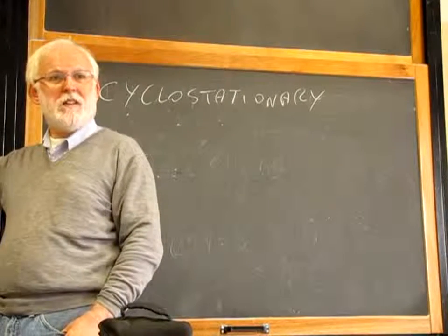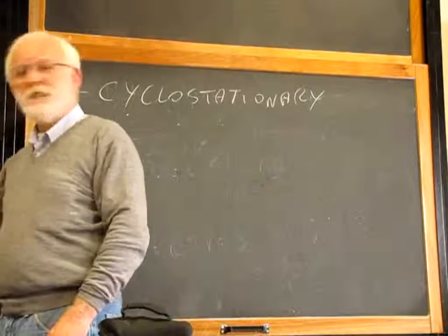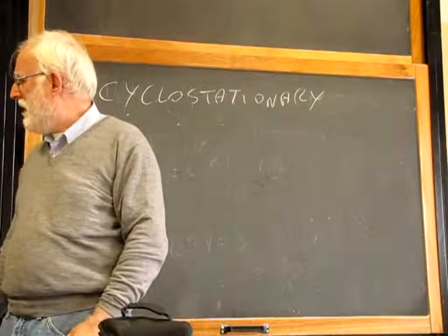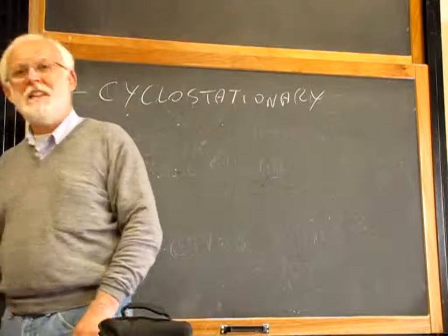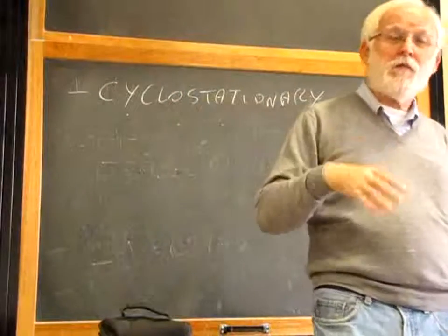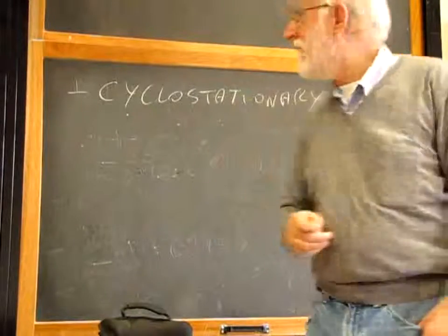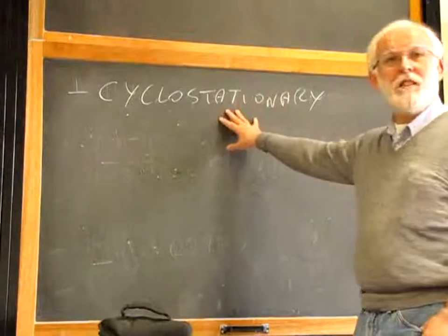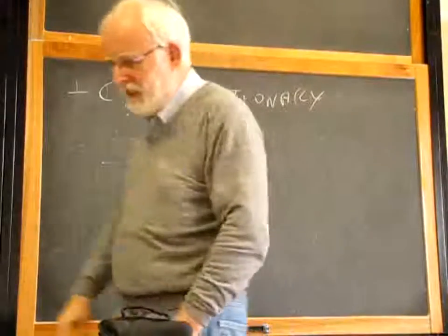We won't remove these because there is a very small effect. Efficiency won't be 1 anymore. We will find out the output ripple. Actually, we don't find out the output ripple. We will design our converter to give us a given output ripple, no more than, and then we'll give you the specs. And then, at the beginning, we'll use a cyclostationary condition, meaning all cycles are the same, and then we'll remove it this way.